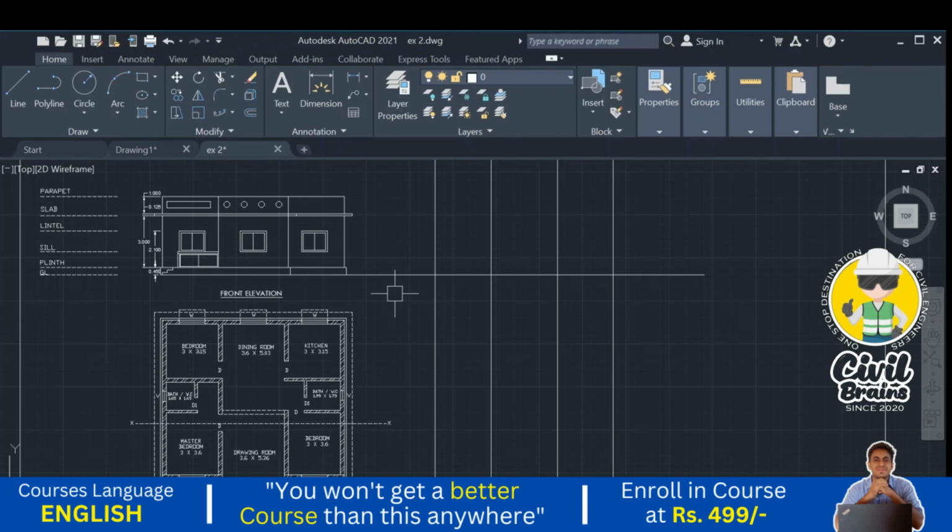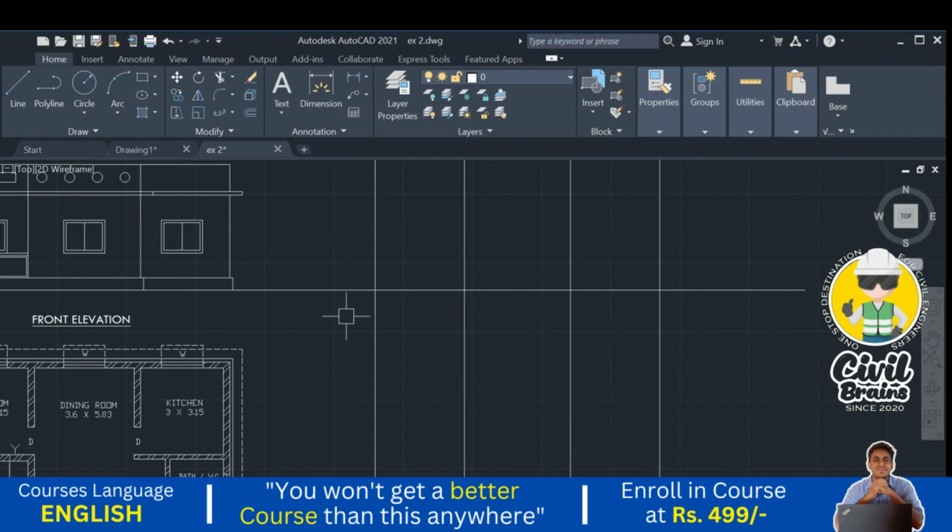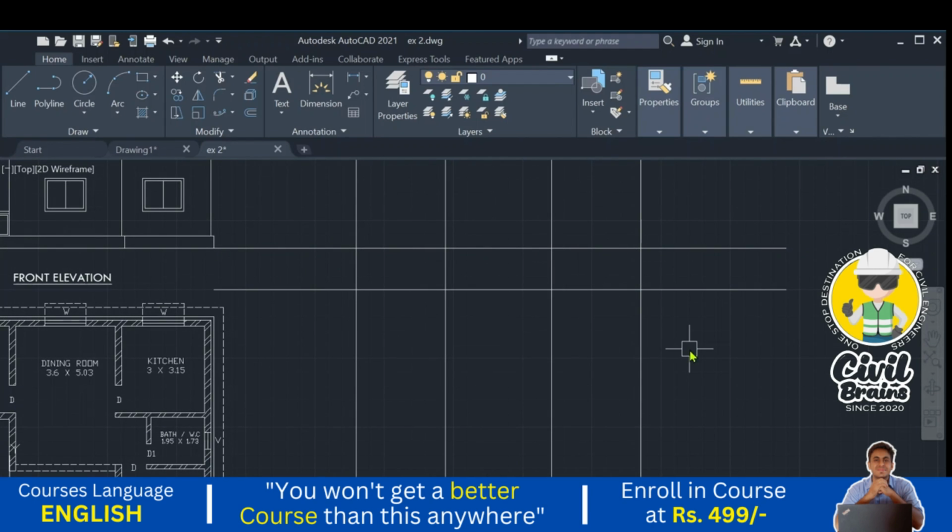So normally, as per the standard, minimum we need to go 1.5 meter, or up to the hard strata we need to go for the excavation. So minimum excavation is 1.5 meter. So I am just considering 1.5 meter. Offset, I just enter 1.5 meter. So minimum depth of the foundation is 1.5 meter. I just delete this one.